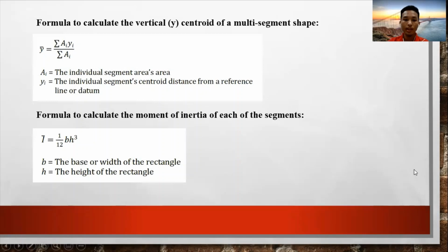In our project, we are going to calculate using MATLAB the second moment of area acting on four types of beam: I-beam, H-beam, L-beam, and rectangular beam. By using this program, engineers can determine the center of mass of the beam section. This program is also useful for beam analysis when the moment of inertia is required for calculation, such as shear or bending stress and deflection.